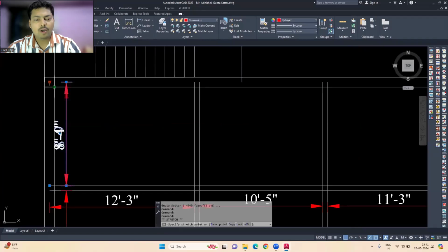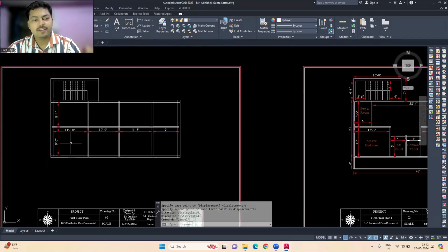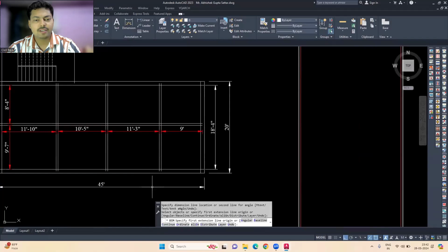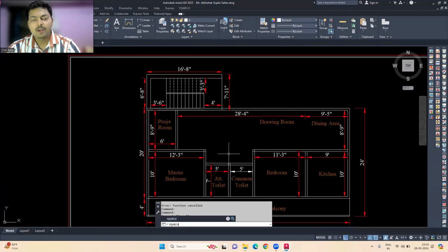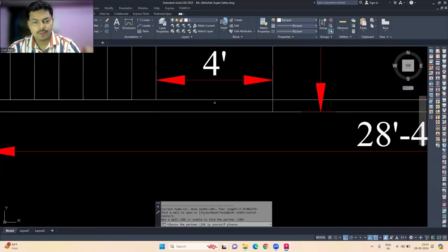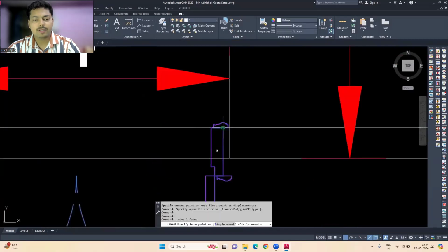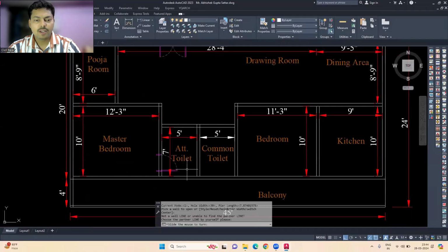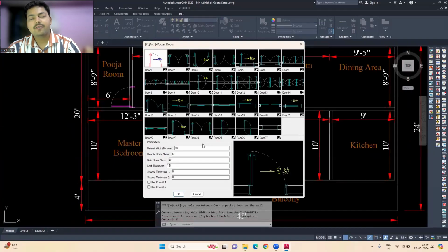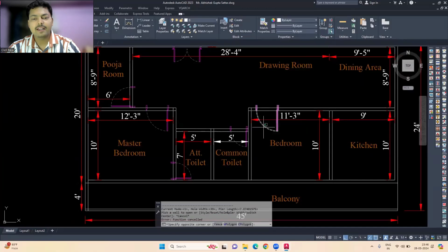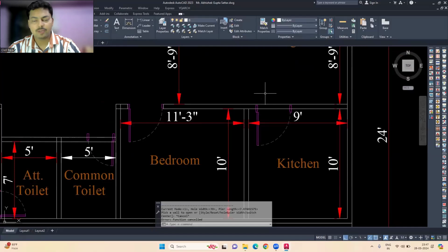Okay, now on the ground floor we need to make 10 inches walls, so I am just making the changes in the plan, and I am just making the ground floor plan over here with 10 inches wall. Then you can see over here I can place the doors. So I don't need to finalize the doors right now. So I will just give a tentative places of the door because this is just a concept and not the finalized plan. Once the concept is finalized by the client, we can clearly place the doors and the windows so that it can look appealing to the eyes.